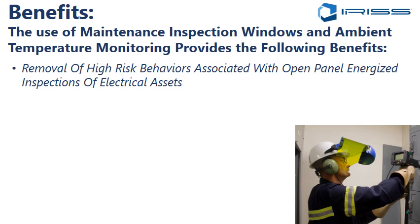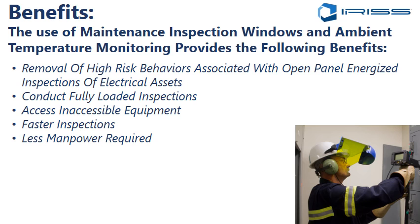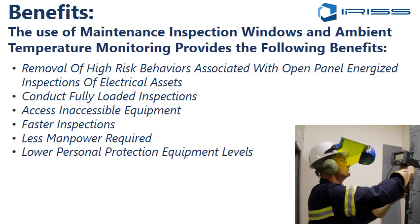We remove high-risk behaviours associated with open panel energized inspections of electrical assets. We conduct fully loaded inspections, which is really when we want to do them. We can access inaccessible equipment, so irrespective of how high the HRC level is, it doesn't matter because the panel remains enclosed and guarded, and I'm not exposing myself to energized work. So I'm literally looking through a maintenance inspection window, taking all of my readings and moving on. The inspections are much faster because there's no PPE or panel removal. Less manpower is required, again just one person with the measurement equipment doing his job. Lower personal protection equipment levels because again enclosed and guarded.